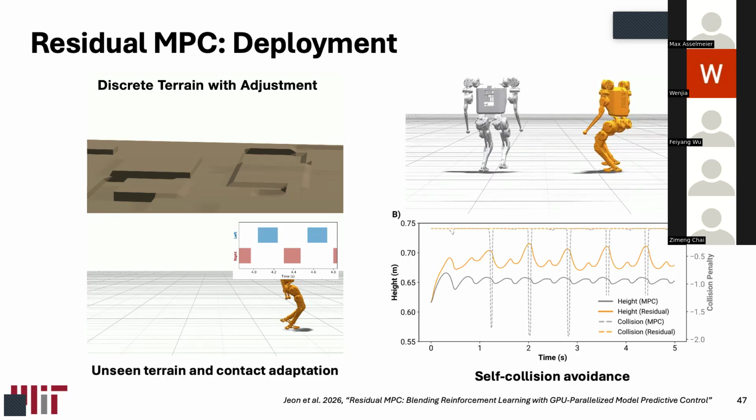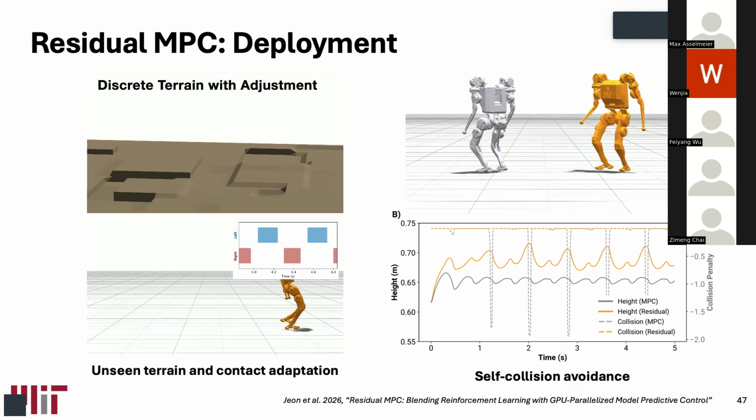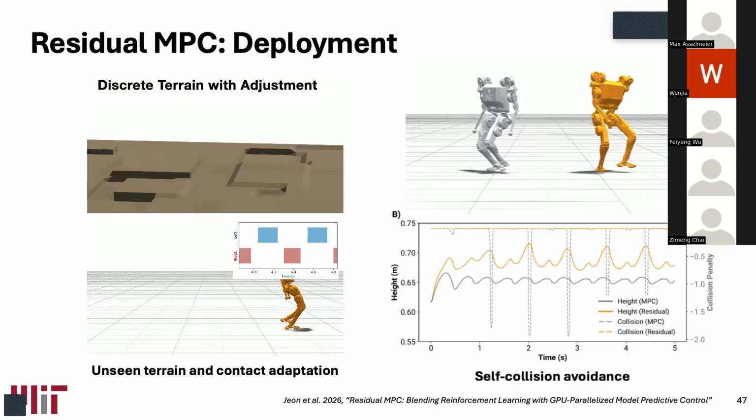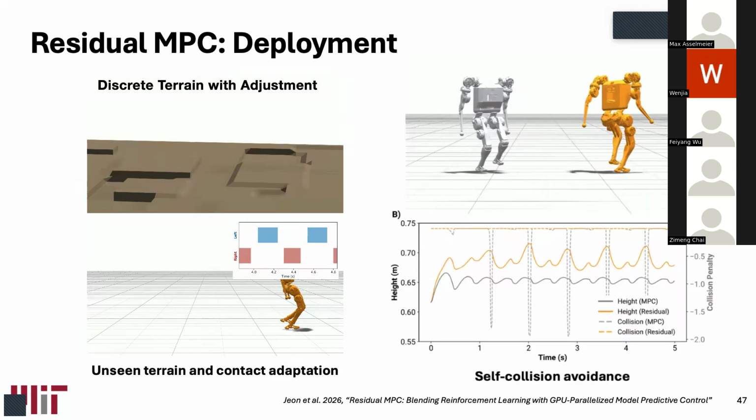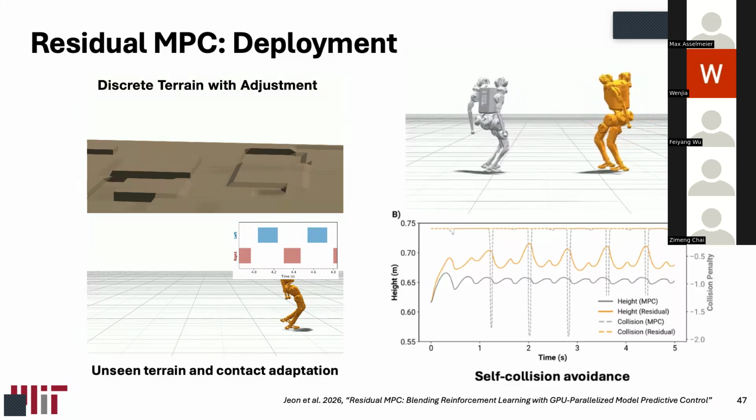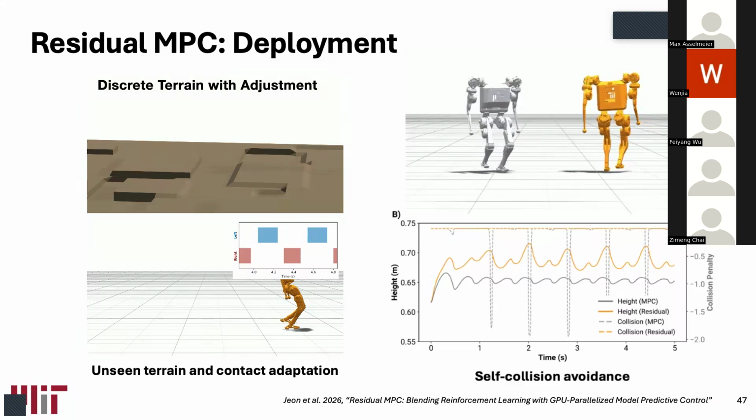So what is the output of the MPC? Is it ground reaction forces? No, the MPC is a kinodynamic MPC. So it outputs ground reaction forces, q trajectory, and q dot trajectory. I then map that to torques with inverse dynamics. Then the same set of parameters for your RL does. So you have this parallel architecture, and you literally sum them together. I do the standard RL law where you have joint set points, and then I just smash the torques together.